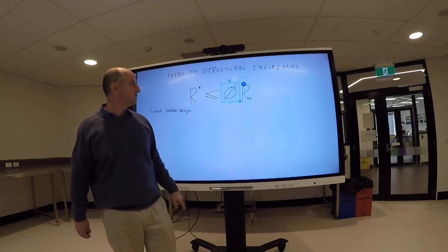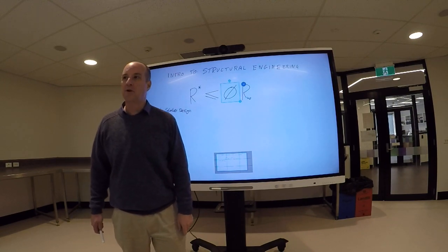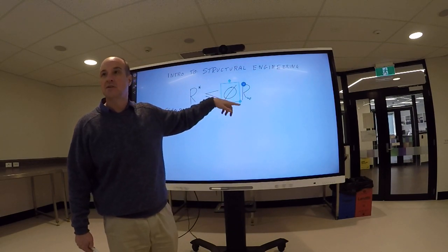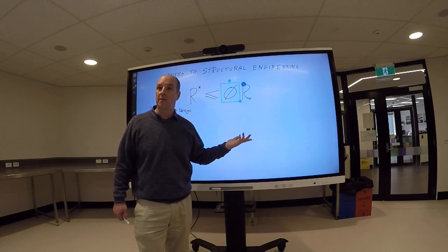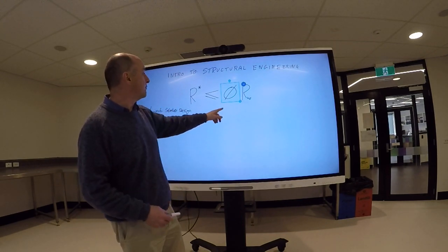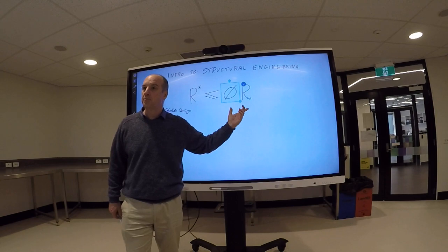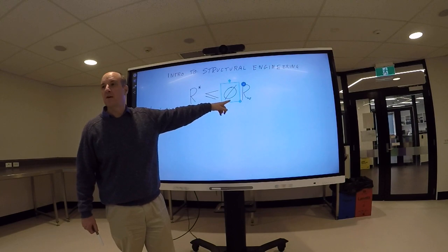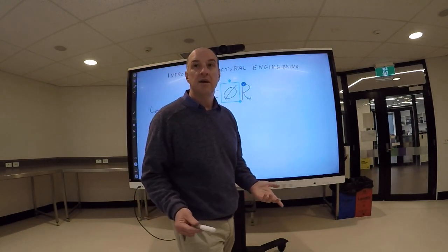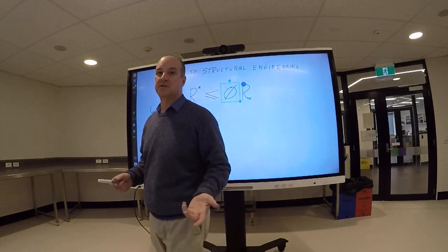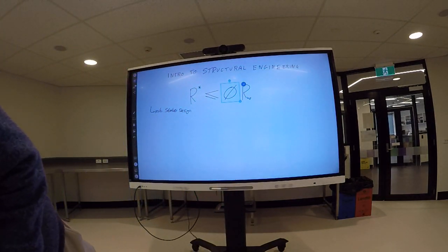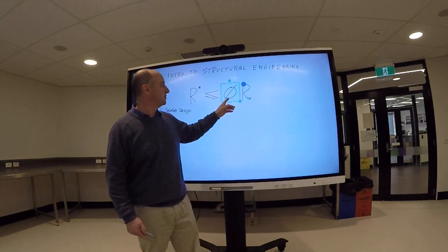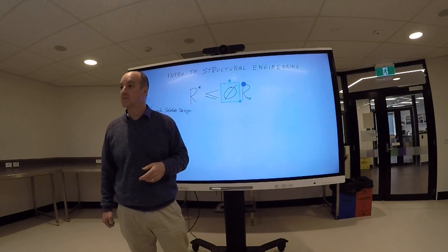The phi factor is what we call the capacity reduction factor. And that varies according to the situation and the materials you're using and what you're actually designing. So, for example, if we are designing a steel beam, the phi factor is almost always 0.9, okay? That's a reflection of the fact that steel is a pretty good material. It's got good consistency, we know what it's about. We can assume that it's going to be 90% as strong as it is advertised, all right?